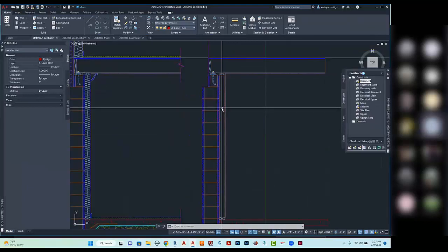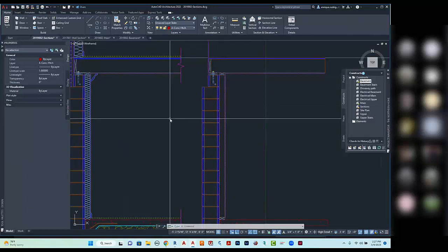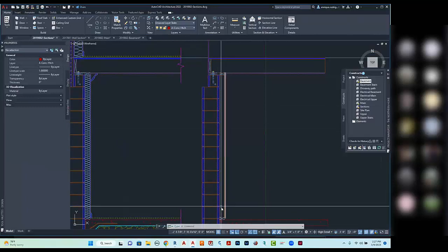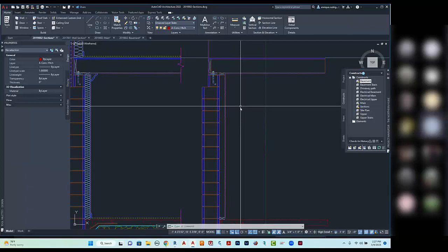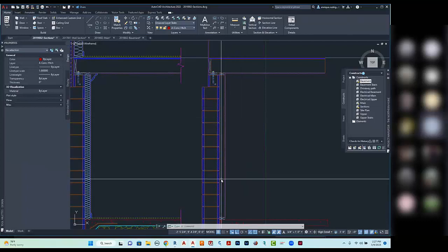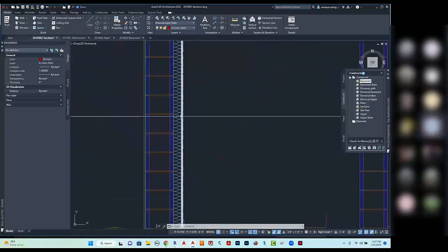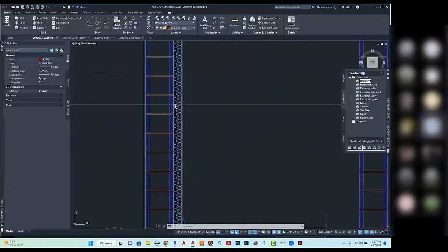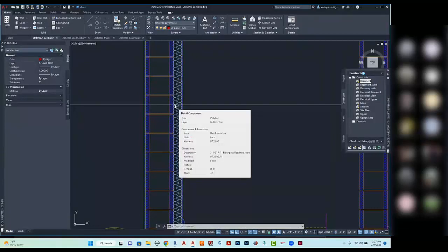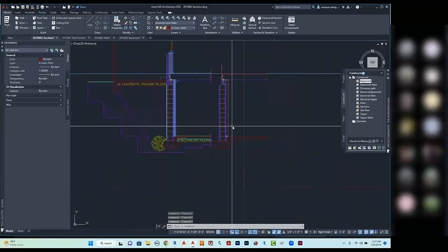One of the things about this stud wall inside of the block is that it can also be used for electrical boxes, etc., but it can also be used for insulation. So that's what this element is right here. This is called batt insulation. Keynote is 721, and it's 3.5-inch R11 fiberglass batt insulation.